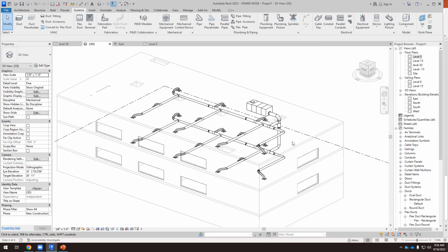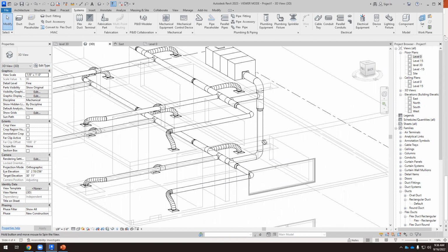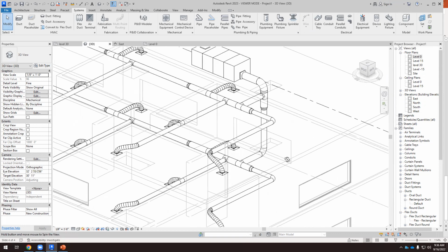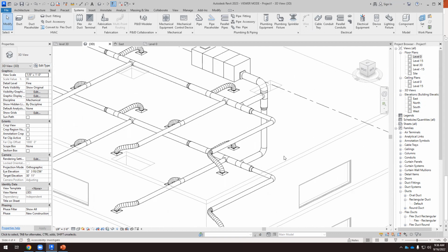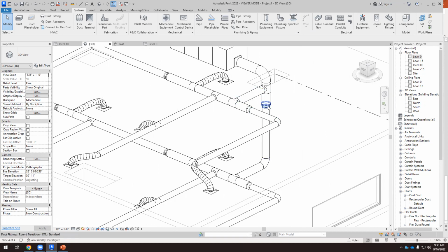Well, take your time. This is probably the most difficult thing we can do today. And in Revit mechanical systems in general, this is probably the most difficult thing: connecting two horizontal branches to a vertical pipe. And after the first branch, we have a reduction, and then we connect this to this one.